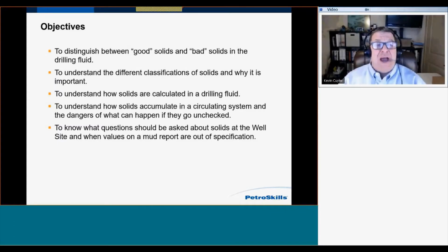I'm going to share how we calculate the solids content and the types in a drilling fluid. We're going to talk about what happens as solids accumulate in a drilling fluid and in a drilling scenario, and what can happen if they go unchecked. We're also going to talk about specific properties of solids, and what questions we should be asking when we read a mud report. What's important to know about solids? What should be going through our mind when we read one? What are what I call unrealistic numbers around solids? What are fuzzy numbers around solids? We'll talk about that here today.